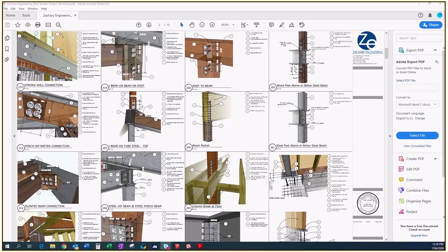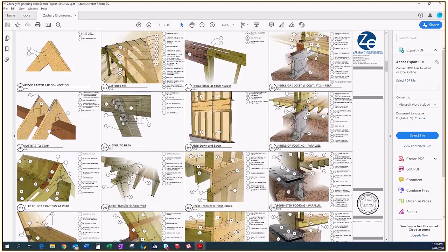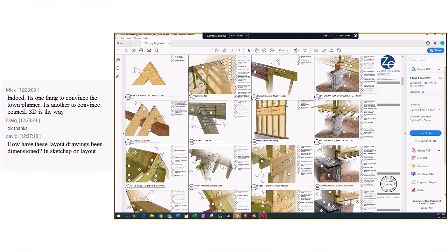And this is powerful, being able to see it even with color and texture, which is why a lot of people doing 3D details are including the color and texture. So, for example, you're not going to be putting every screw in. Even in the virtual design and construction model, you're not going to put every fastener in. But in the 3D details, you are, because there are important things that you're going to be passing on to the trades on site. And again, these are just being presented on a 2D drawing, on a construction inside of layout.